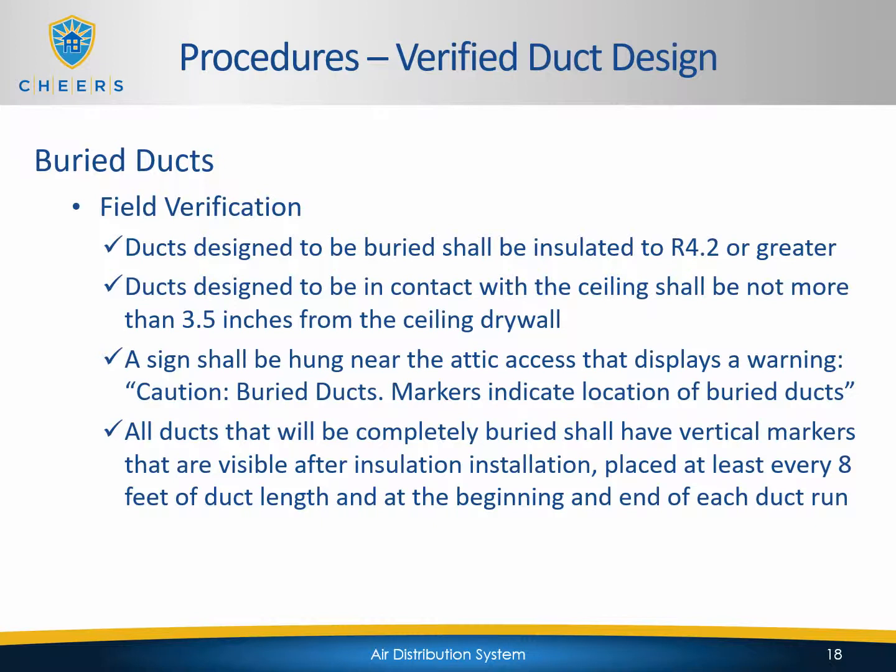You'll need to have a sign that's hung near the attic access that displays a warning: caution, buried ducts. Markers indicate location of buried ducts so that other contractors and trades don't go around and step on those ducts on accident and crush them.